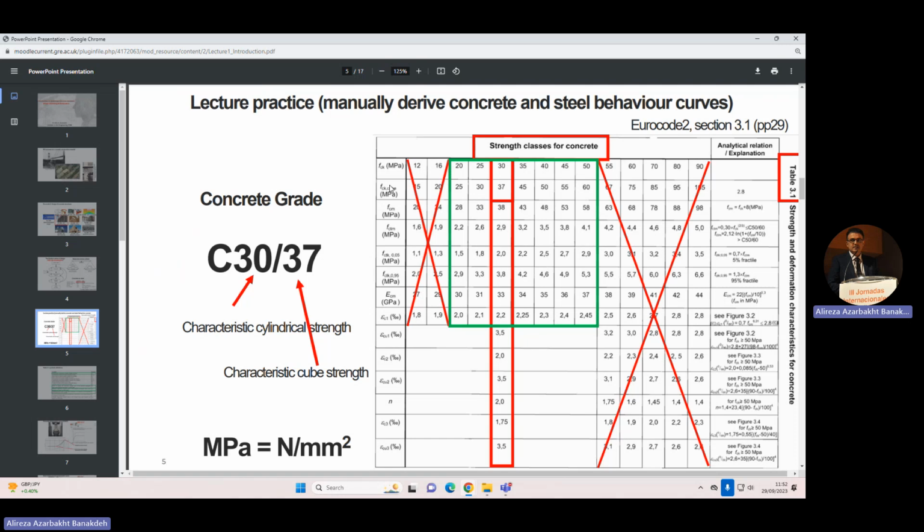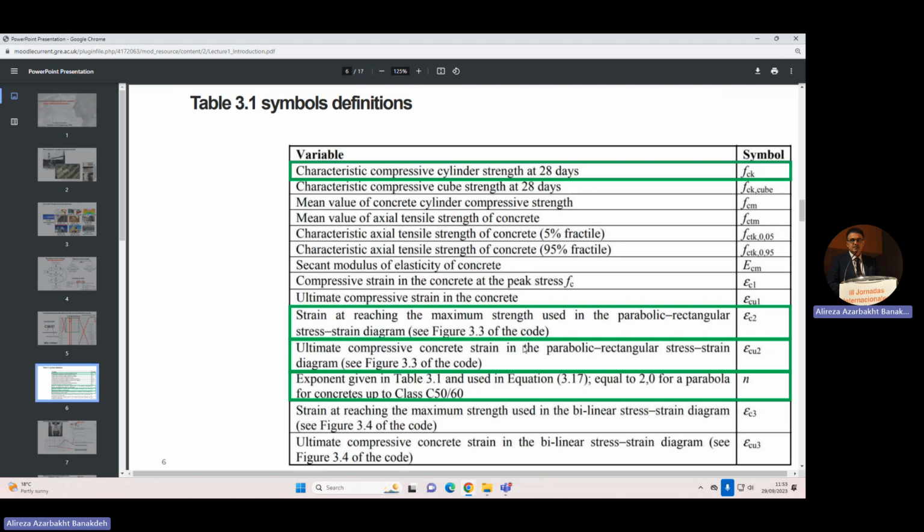That concrete is a hybrid thing. It's a mix of concrete and reinforcement. The behavior is different. This is the pure concrete. Okay? Now, this is just the pure concrete, and we don't really use 37 in any sense. That's there really to respect a couple of old codes. I don't know, 50 years ago they used to use that, but at some point they changed to cylinder type of strengths, which is 30. Okay, we only use the first number. So are you happy? Everybody happy with the table and these 4 parameters?